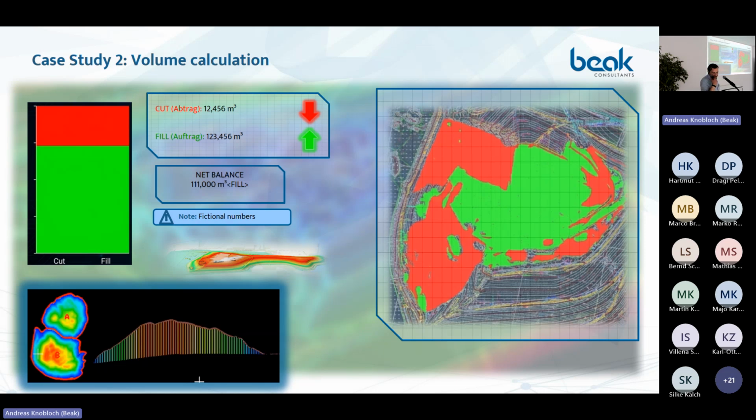And we saw different things during this type of work, but they are not shown in the images. We saw also depressions because this is a waste mine, and because of the waters that run through, we could see depressions on the ground, like 10-centimeter depressions, that are concerning for the client itself and for the structure stability.